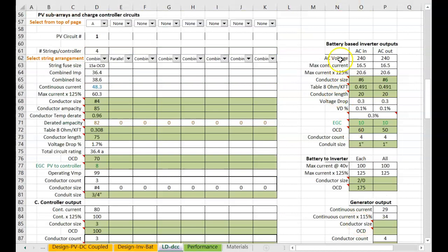And then you do the same thing. You have your AC input and output. This goes to the protected loads panel, and the input comes from the utility or from the generator. And so you really want to defer to the manufacturer specifications on this. They usually do specify all of these, and you want to put in your conductor length so that you can get your voltage drop. Notice we have 2 voltage drops. One is from the output and one from the input, and then they're combined.